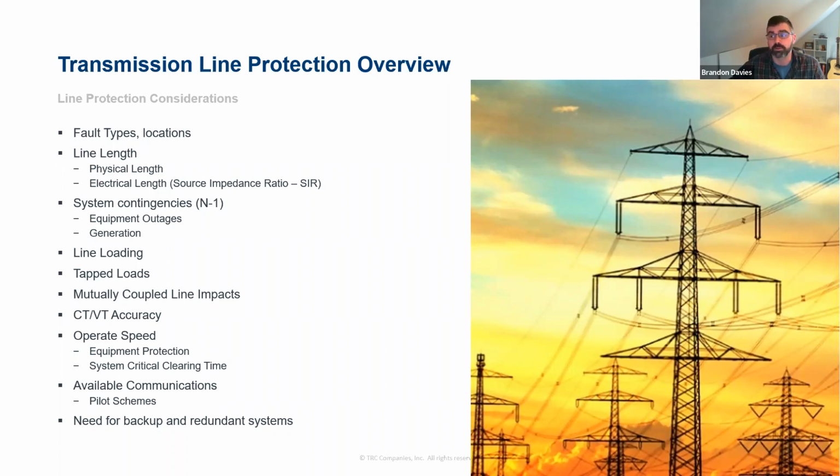Line loadability is a big one. As protection engineers, we want our relays to operate for faults, but we also really don't want them to operate under load. If you're in a very high load condition, the last thing you want is to further stress your system by tripping your transmission paths off from a relay operation. So we'll talk a little bit more about loading later. A lot of the examples we're going to be talking about are going to be very simple two-terminal lines. So you've got two stations connected with a transmission line in between.